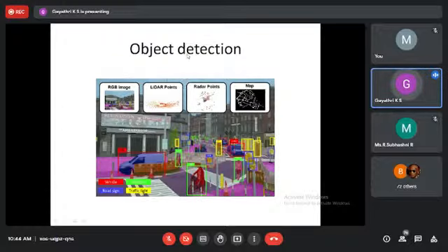So this algorithm, when you give these inputs to it, is one of the machine learning or deep learning techniques that is able to classify the different objects around you. This is the second component that an autonomous vehicle should focus on: identifying who is around me. The other vehicles are called agents, and my vehicle I call the ego vehicle, or the autonomous vehicle. So the second step is to identify what objects or agents are around me.